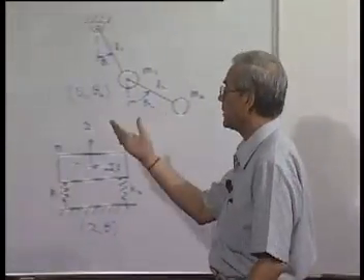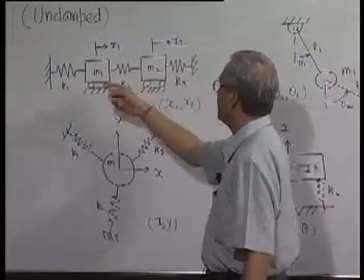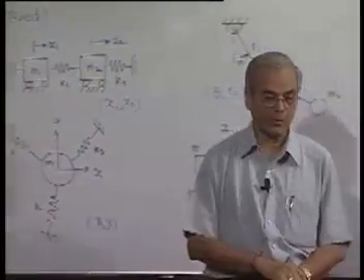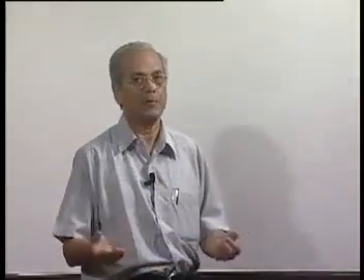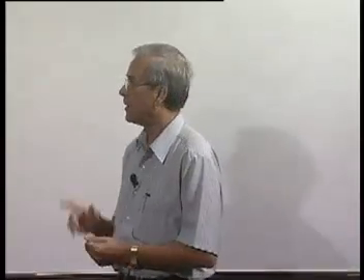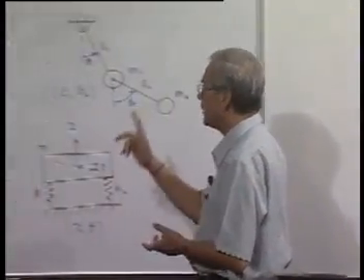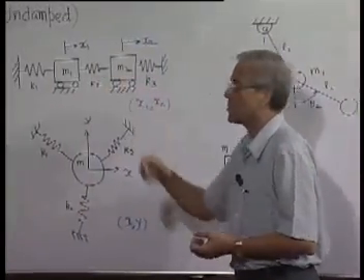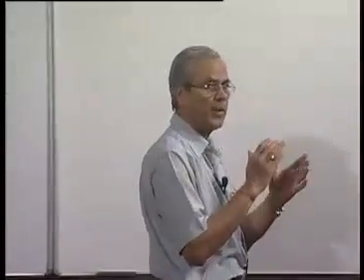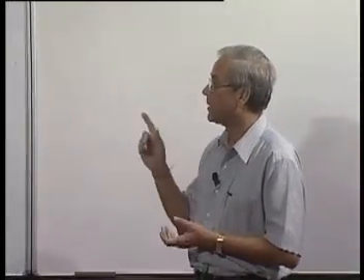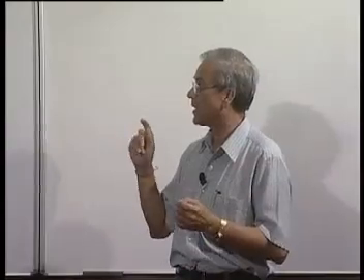In case of 2 degree freedom system, suppose this one, I disturb somehow. Will the bodies execute simple harmonic motion? The answer is no. That is a very fundamental difference with the single degree freedom system. That means the free oscillation of this will not be necessarily a simple harmonic motion if the displacement is given in an arbitrary manner.